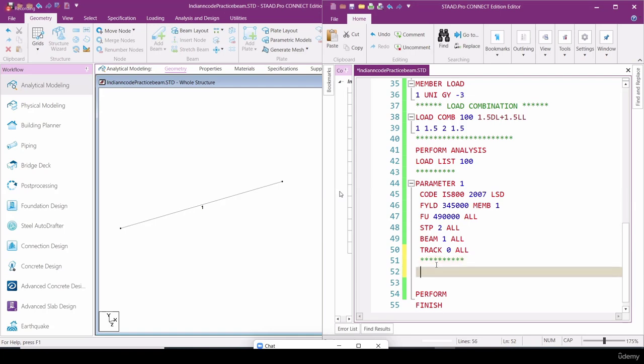And then next, so that you guys don't get confused, I'm taking every section with comments, so that you guys follow clearly. If every part is completed, that's why I'm putting some stars. If any line starts with a star, that will not run in the design, no problem. Okay, and the next one, we need to give design parameters related to the beam. So unsupported lengths: what is the unsupported length in the buckling axis in the major direction? LZ.